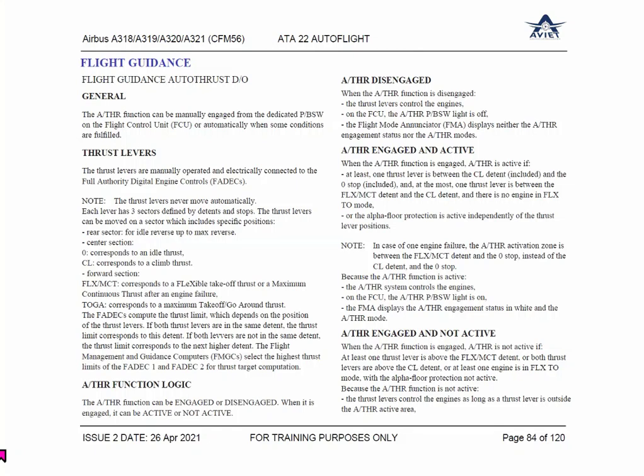Sir, am I audible now? Yes, go ahead. Sir, you were talking about the difference between engaged and active. So engaged means it is waiting for some conditions to be met, but when those conditions are met, then the relevant system will be activated. Like for the auto thrust, it is engaged when we manually switch on the auto thrust before takeoff, and then when the lever is moved to the TOGA position, it will be activated into the system.